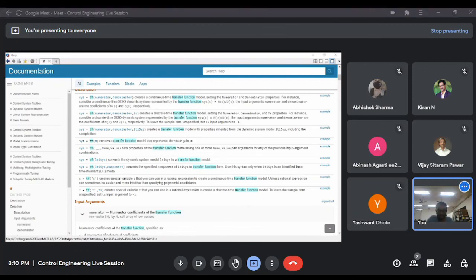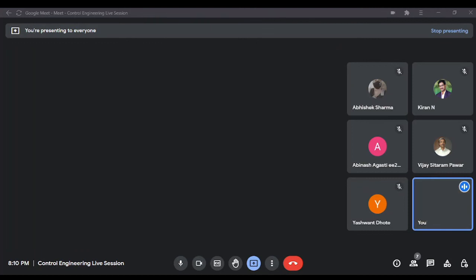Then, okay, let's search for how to plot the root locus. Okay, there is this root locus. So then it says, suppose you give a transfer function and type rlocus, like you define this transfer function by this command, then say type rlocus of that system. That will give you a nice root locus. Then further commands are there, how to plot multiple system models and how to look only for a certain gain range of things and so on.